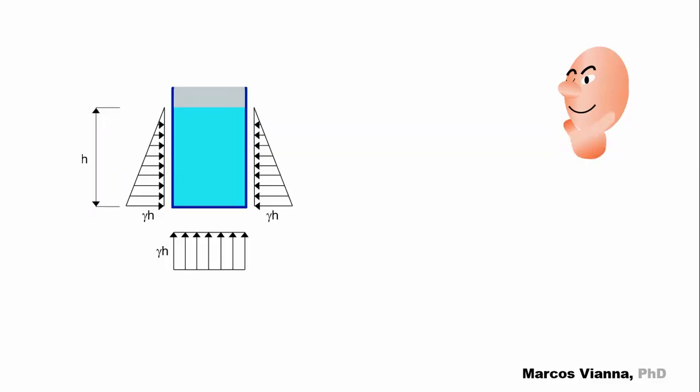Here is a very simple scenario in which a tank is full of water and whose free surface is exposed to the atmospheric pressure. As we did in the preceding problem, we'll assume that the pressure at the free surface equals 0. There's a linear variation of the pressure with the depth. As the bottom is horizontal, there is no pressure variation here.